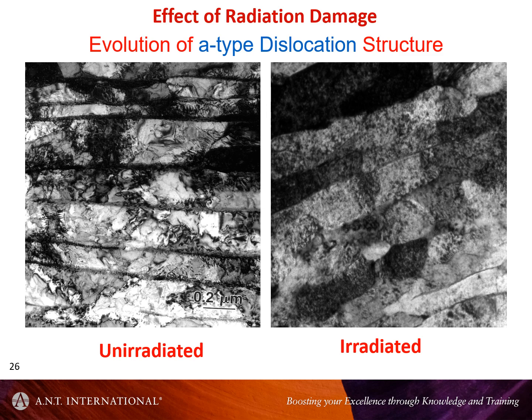I mentioned cold worked structures. I mean, often if we have a cold worked structure, whether it's a zircaloy or a zirconium niobium, typically, because it's heavily deformed, the grains are flattened into platelets, pancakes like that, and they contain a very high density of dislocations.